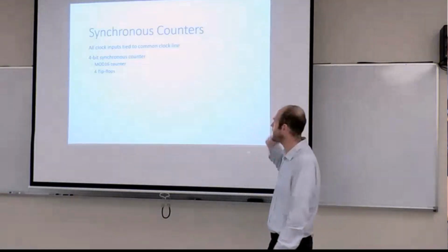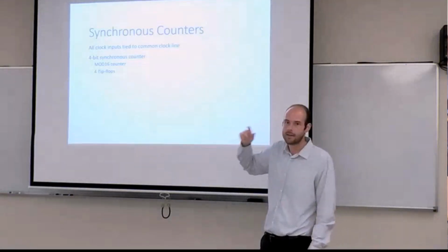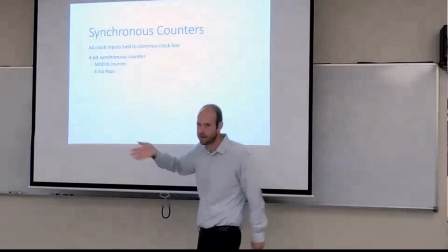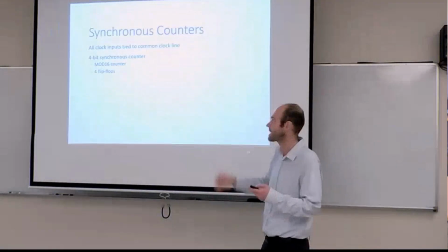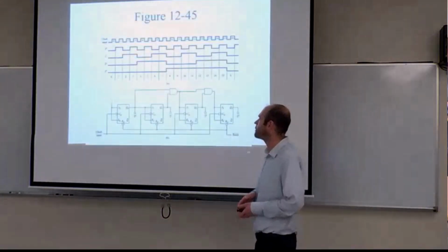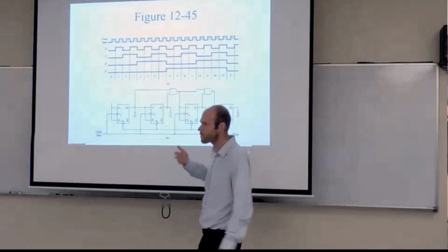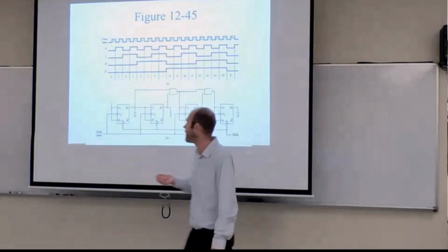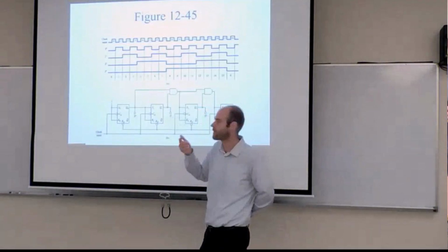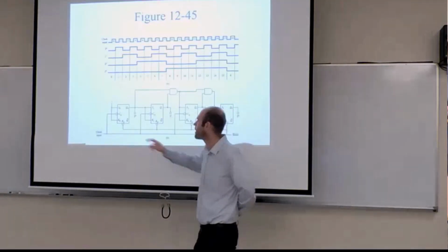Specifically, the timers on a modern microcontroller system are probably synchronous, because we're talking about 8 and 16-bit or more size counters. To make synchronous counters, we do require some external logic, because the bits have different relationships to how they flip.